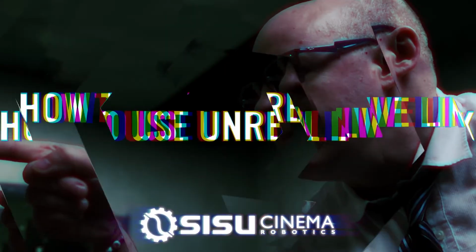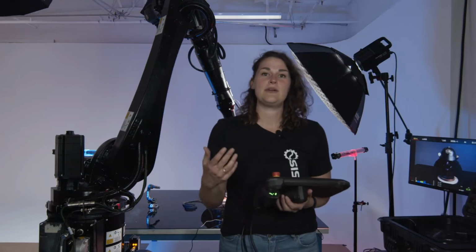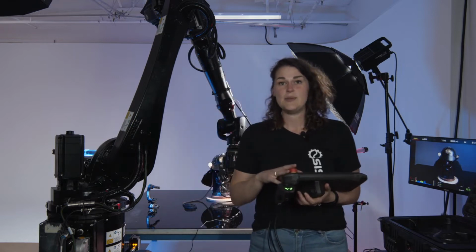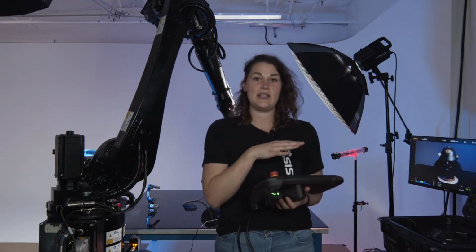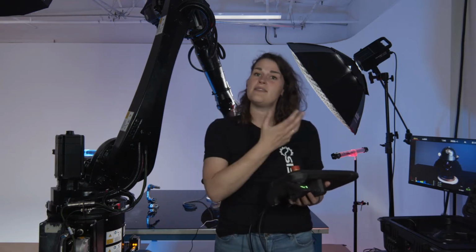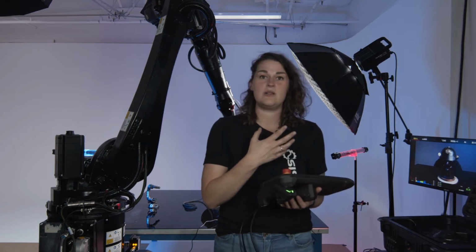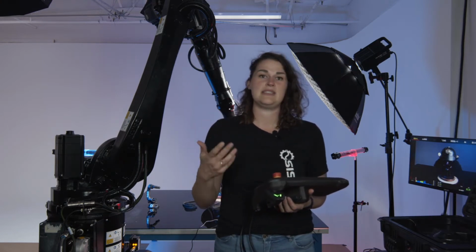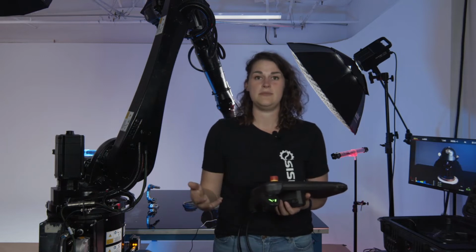The Unreal Engine Live Link plugin is going to allow you to get live position and camera depth of field information from Sisu Lab into Unreal Engine so that you can do things like live composition with a green screen and work with an LED wall to live update the LED wall based on where your camera position is, as well as that focus and iris and zoom information.